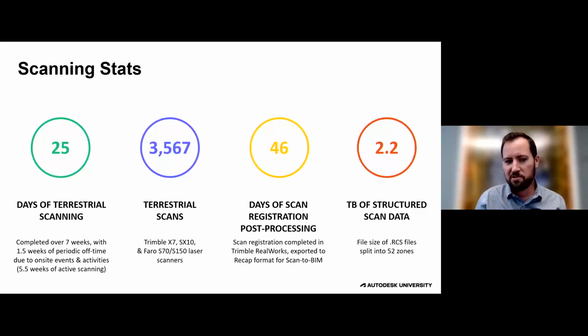It was approaching 3,600 total scans, which was our largest scan project to date with those 4 scanners. And then on the back end, it was about 46 additional days to complete registration, stitch together all that data from multiple scanners, even though we did have some of the automatic registration happening and manual registration as well on site. And then total is about 2.2 terabytes of scan data in the recap files that were ultimately linked in for modeling in Revit. And we split those files up into 52 zones, which was necessary to reduce the file size to looking at certain areas, certain chunks of scan data at any given time based on file size.